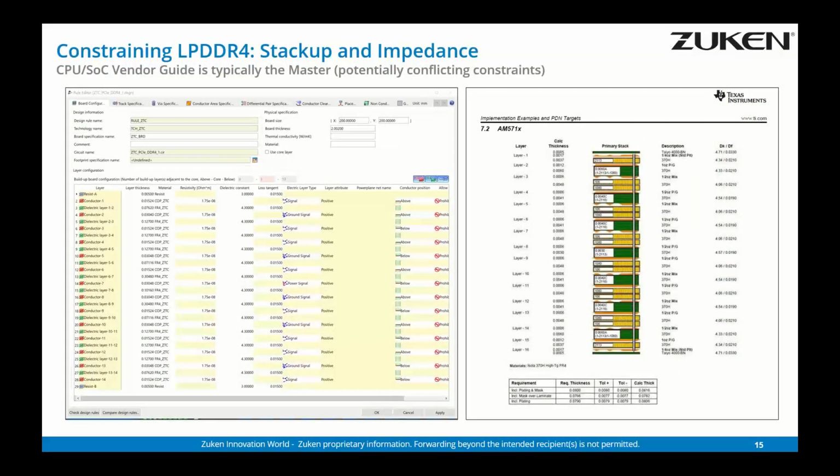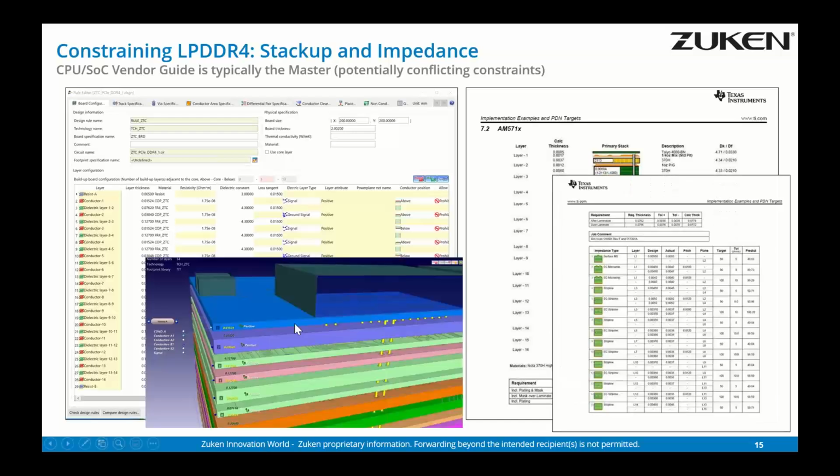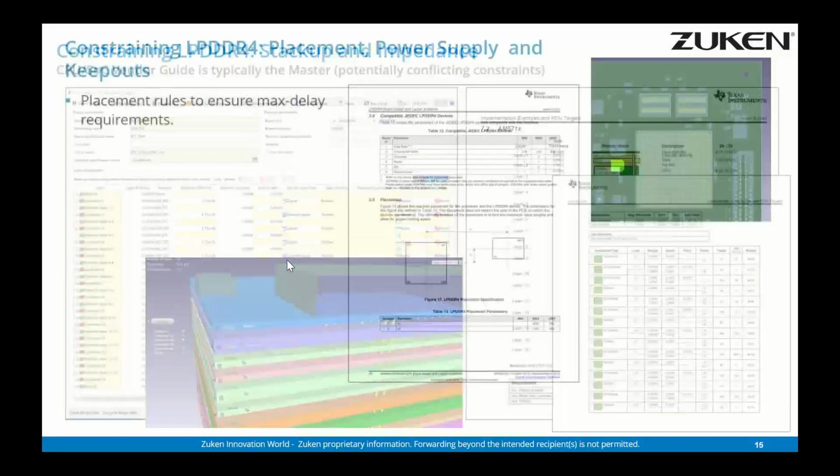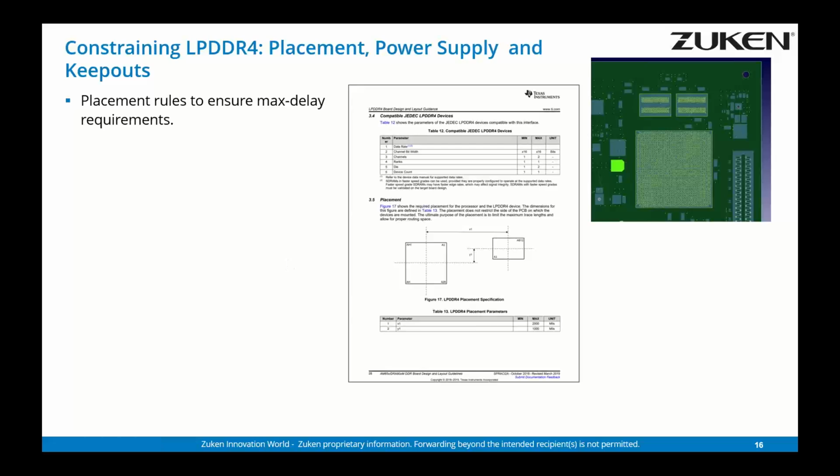So you have to implement these different impedance rules, these stack-up rules, in the CR-8000 process, and then probably use what-if capabilities to optimize these structures to arrive at the proper impedance for all the different required signal cut sections. So CR-8000 allows you to create proper rule width stacks coping with all these different impedance situations and cut sections, whether you have to implement the structures as a microstrip, an embedded strip line or a coupled strip line. That's available in the technology definition already in the front end.